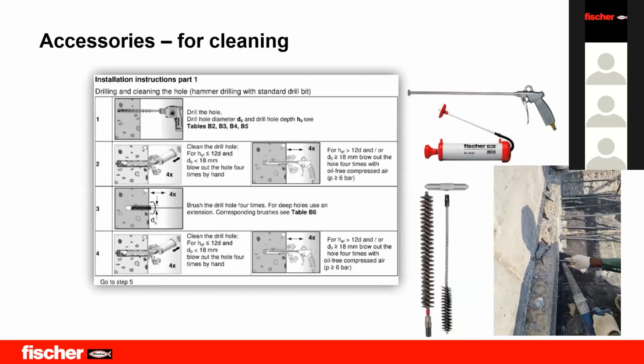At the same time, cleaning is the next most important, and now everyone is aware that cleaning is one of the most important things that has to be done when you're doing an installation. You can see a live picture where blowing is happening and brushing is also happening. At the same time, you can see the installation steps. These steps are available in our ETA of each product. That is why, again, approval is valid, because once you have this approval, all the installation steps, all the gelling time, curing time, and what load you're looking for will be there in that ETA.